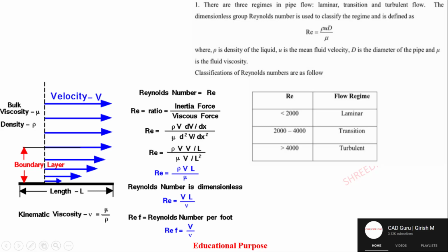Okay, so you could see this is the viscous force and the Reynolds number. So if I consider Reynolds number less than 2000, we need to consider that as a laminar flow. If you're considering transition, 2000 to 4000, and turbulent more than 4000. Okay, so while defining this parameter, we'll keep it automatic sometimes. If you know the Reynolds number, you can choose whichever you want. Okay, the software is capable of it, now which exactly we need to choose.